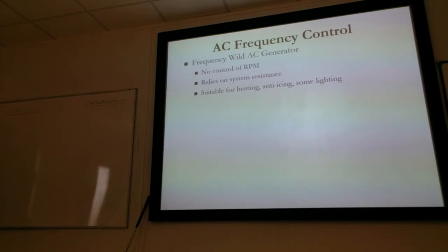But most of the time it's no use to us. So what we tend to have is constant speed drive units. Now in fixed wing aircraft, gas turbine engines, you're going to need to run a constant speed drive unit because your RPM isn't constant throughout your flight.